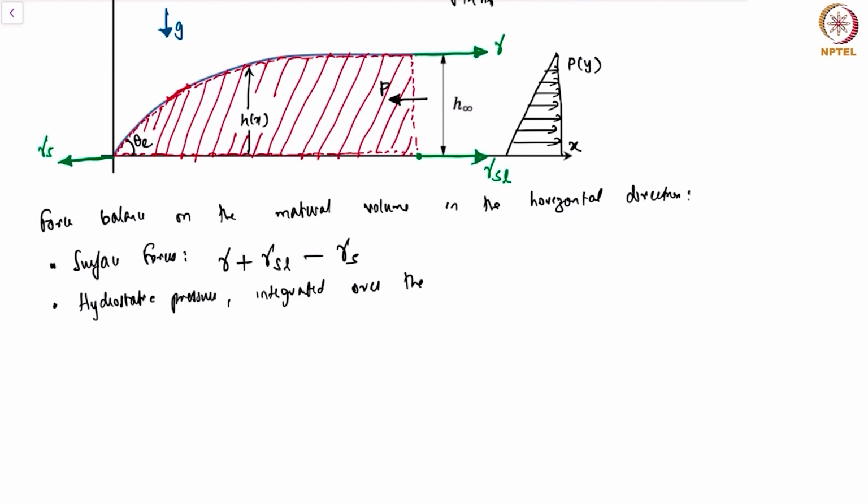over the thickness of the liquid. And what is this hydrostatic force? We'll call it P, and this quantity essentially goes from 0 to H infinity of rho g times (H infinity minus y) dy, right?